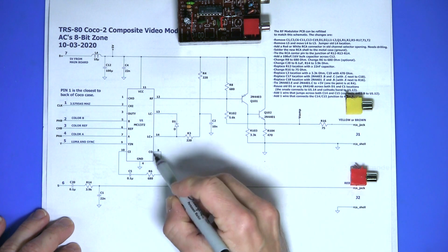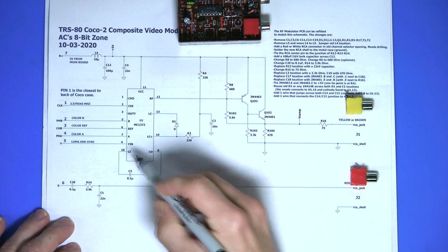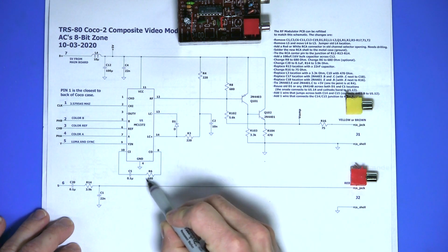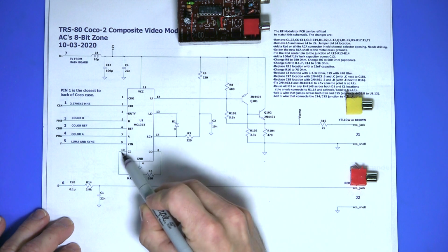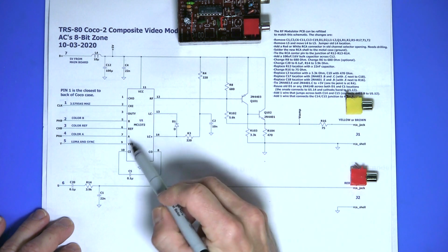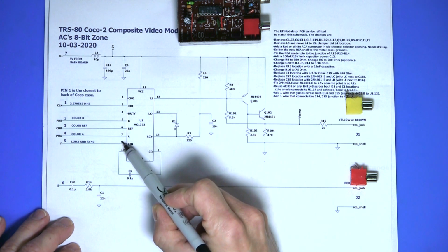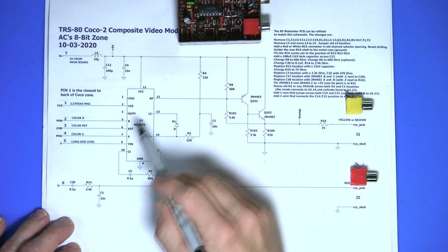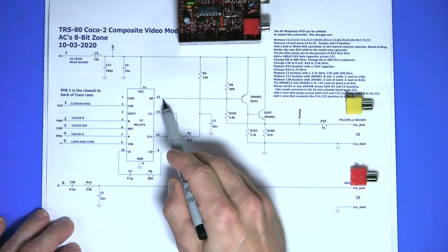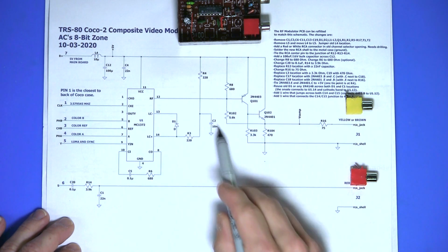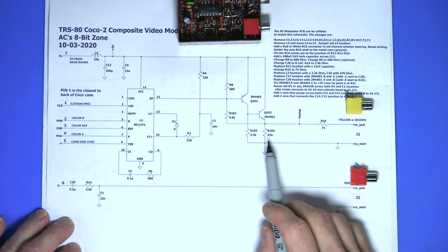The chrominance output is looped back in, and I've modified this resistor value, and it comes into pin 10, and the Luma on 9 with the sync embedded in it is combined with pin 10, and that's output on the RF pin 12 and then amplified by this BJT amplifier circuit.